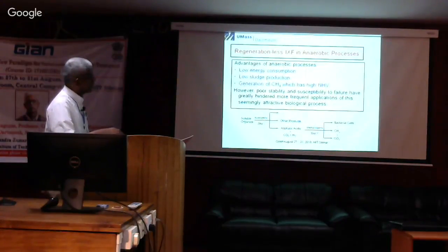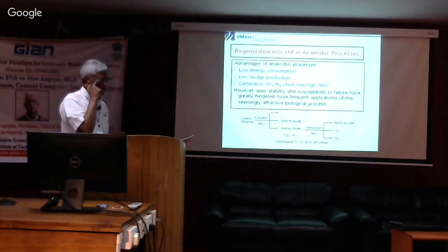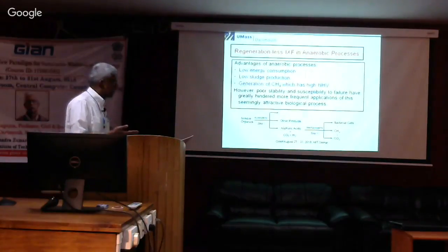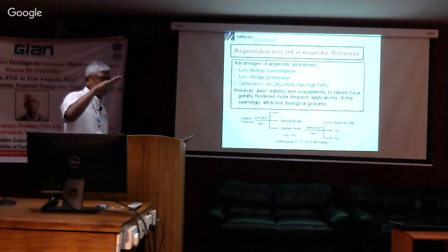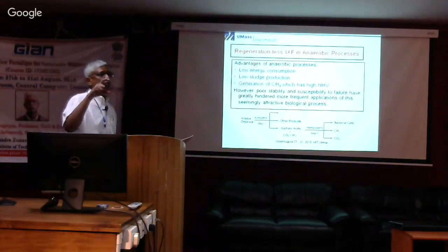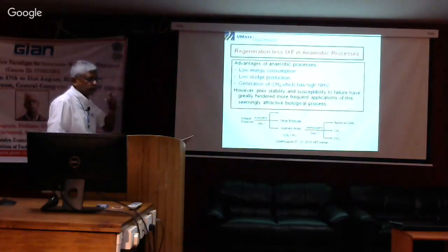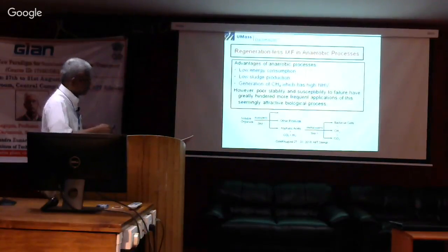The acetogens are doing their job. The methanogens are not doing their job. What will happen is that you will keep forming more and more aliphatic acids. As you form more aliphatic acids, the pH goes down. As the pH goes down, the methanogens stop even more. And slowly the process becomes a failure. It's a negative feedback loop, as we say.